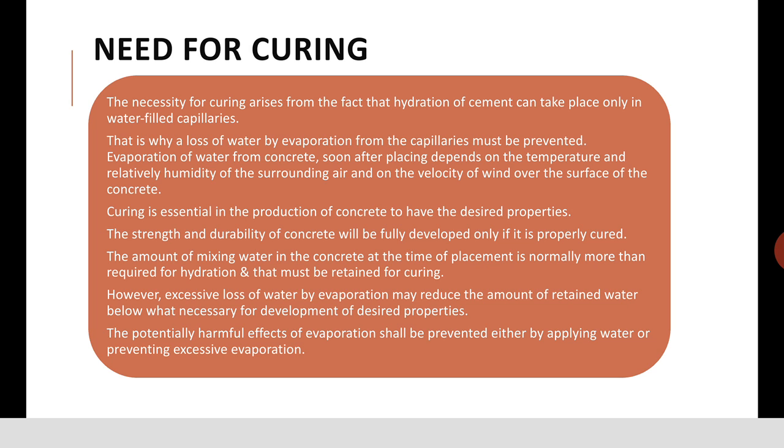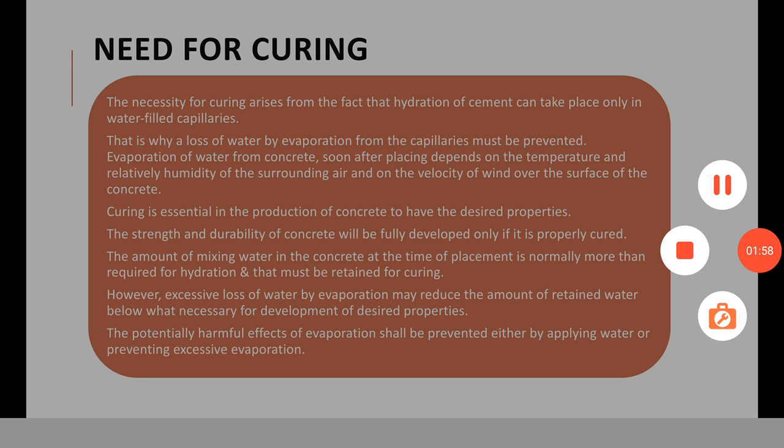However, excessive loss of water by evaporation may reduce the amount of retained water below what is necessary for the development of the desired properties like compressive strength and durability. The potentially harmful effect of evaporation shall be prevented either by applying water or by preventing excessive evaporation by application of curing compound.